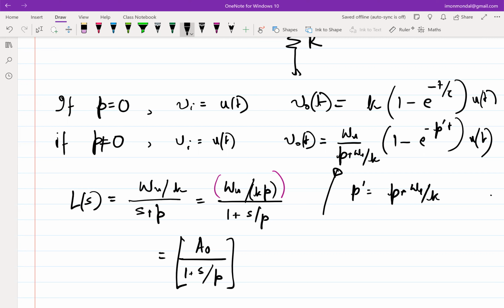When you are approaching somebody to design, and somebody is giving you an op-amp design, in reality, they will not tell you to choose this gain, choose this bandwidth, and so on. They will tell you the top level specifications that they require. From there, you have to narrow down and figure out what that specification essentially means. So this is one example: my output should be accurate within, let's say, 1 ppm, which means your DC gain should be equal to 1 million.